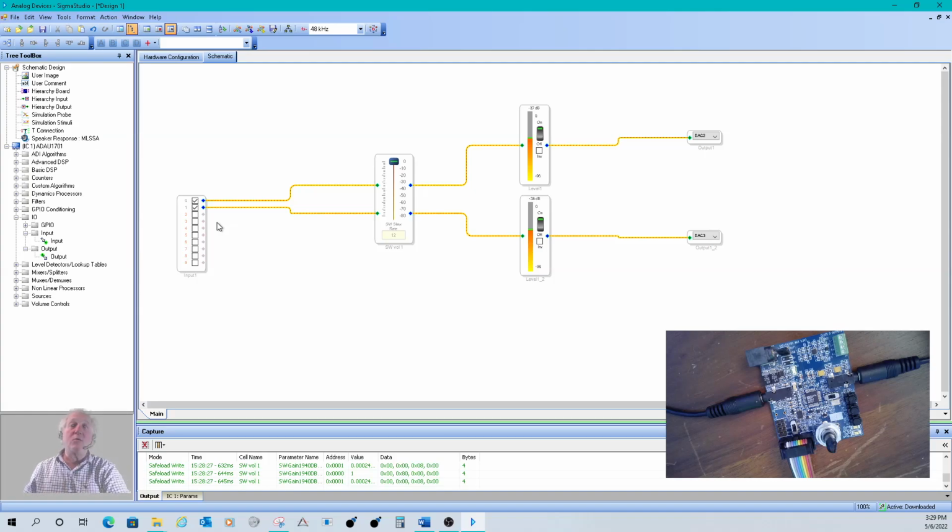So in this case, we have to deal with it here. I mean, it's fine going out, but if I start EQing the low end, it's going to EQ up that DC. If I start switching between signals, you might get pops. So we want to get rid of it.